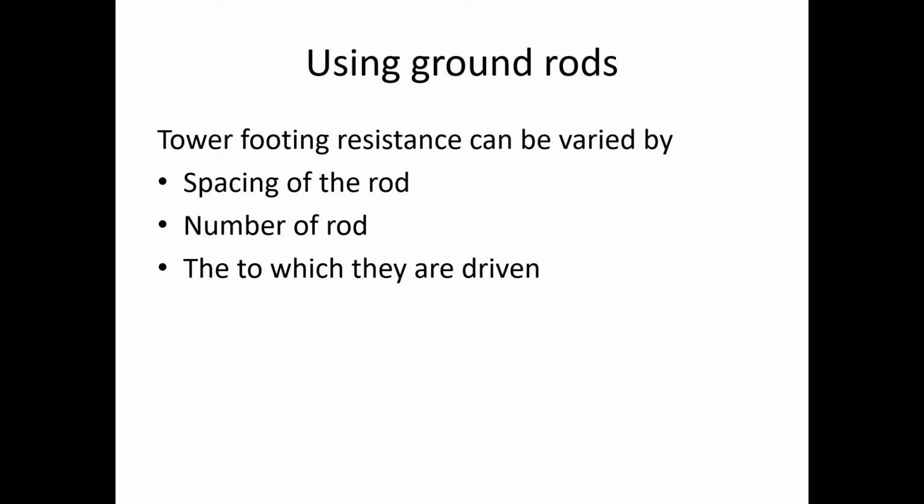Moreover, it should be buried at 3 meter into the ground. And also the tower footing resistance can be varied by varying the spacing of the rods, the number of rods, and also the depth at which we bury them.